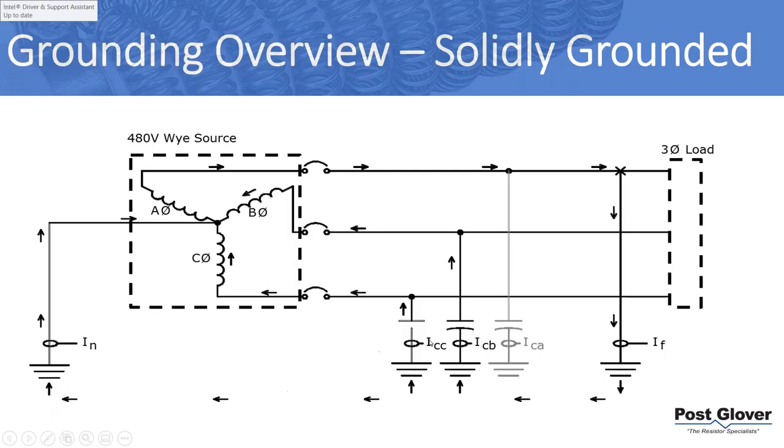The idea is you still have this naturally occurring system's capacitance that's carrying current, although typically small because it is usually a high impedance system. Because you're going to have insulation, potentially you're going to have air, lots of things that are high insulation that's going to prevent a lot of capacitance and a lot of current carrying capability in this path right here.